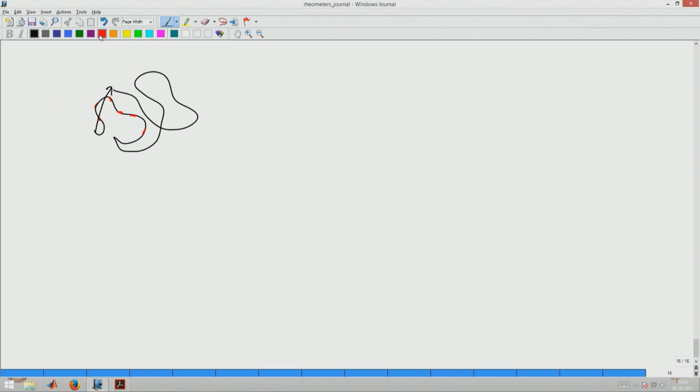So, it is like saying that I have lots and lots of small vectors. If I add all of these vectors, then I will get my eventual end to end distance, and this end to end distance is based on addition of all these dipoles. So, by knowing how the dipoles are orienting in general, I can also have an idea about how the overall molecule itself is orienting. So, in fact, you can distinguish between reptation motion, which is the whole molecule itself moving, using dielectric spectroscopy. You will not be able to do that in what we did in all of our rheology